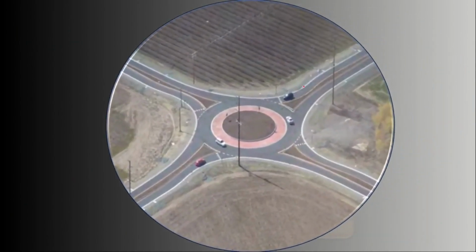Single lane roundabouts have a special feature too, and it's this traversable strip around the center island, the apron. There is a reason behind this traversable strip around the center island, and it's that single lane roundabouts are large enough to accommodate the outer radius of large vehicles when they're making a left turn.